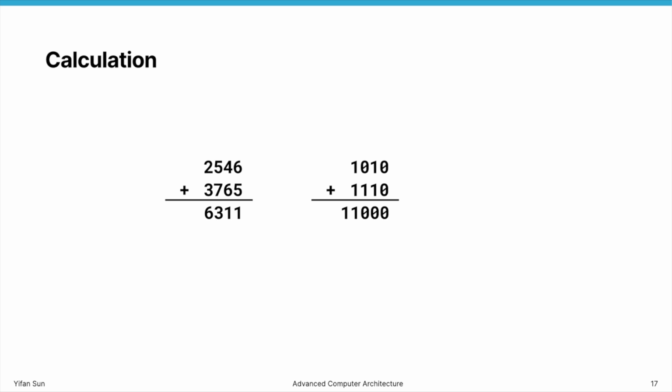So here we basically follow the same rule. 0 plus 0 is still 0. This is real plus, okay, this is not the OR operation. 0 plus 0 is 0. 1 plus 1 is 0, and put a 1 here, right? Now 1 plus 0 plus 1 is 0, and put a 1 here. 1 plus 1 plus 1 is a 1, then put an extra 1 there. Okay, so if we do this type of operation, it's equivalent to doing the same operation in base 10.